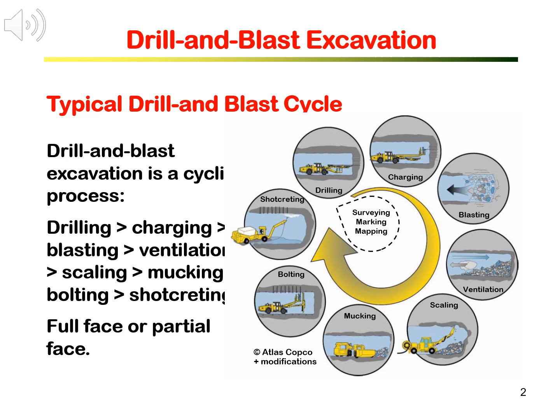Breaking the rock by blasting takes only seconds, but the whole cycle, from drilling to mucking and temporary supporting, takes several hours with modern equipment and machines. Usually, the maximum number of drill and blast cycles in tunneling is 3 times a day.